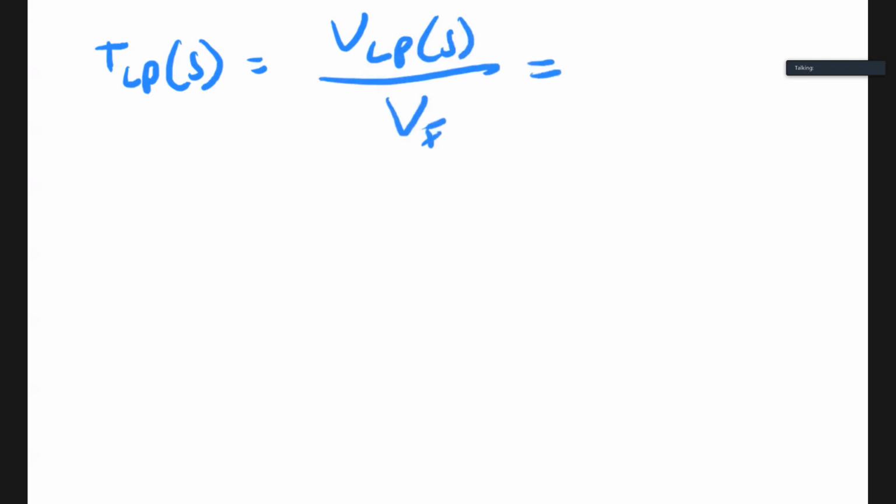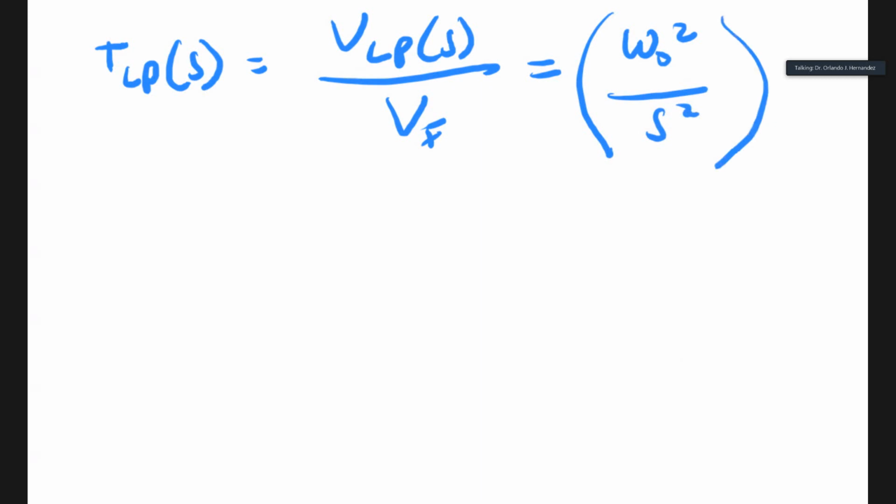So I would integrate twice to remove the zeros at DC so I can get all the DC in. So this would be an all pole filter from that high pass transfer function.